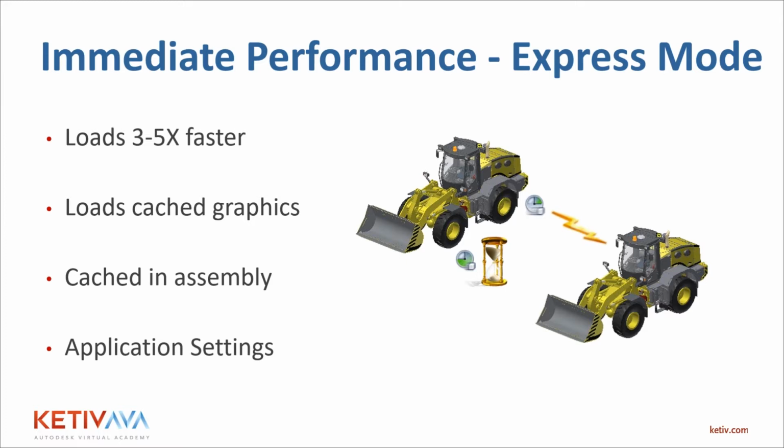Now, your file size will increase on your assembly. It'll increase significantly. So we'll take a peek at that here in just a moment, right? And it'll be cached in the assembly. Now, as you load other files, you edit them in place or you work on them within the assembly, so you'll lose some of that benefit of Express Mode, okay? And the easy fix to that is you can simply close the file again, open it back up in Express Mode, and you're now working with those cached versions of that information, right?